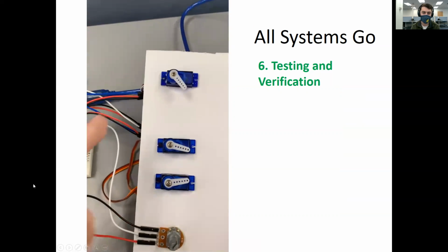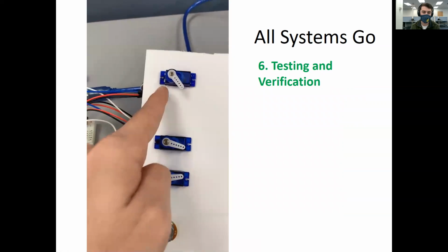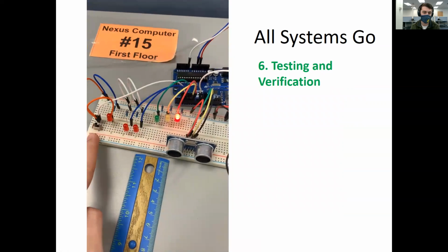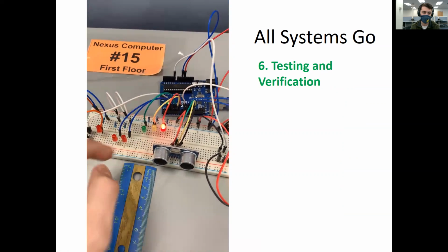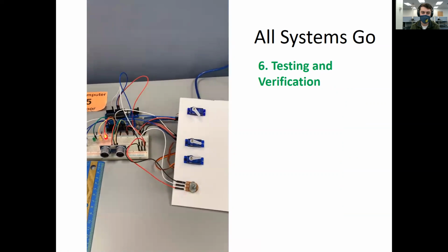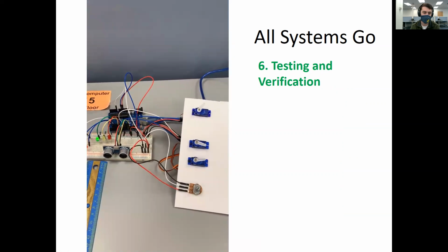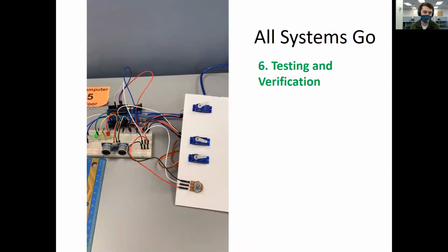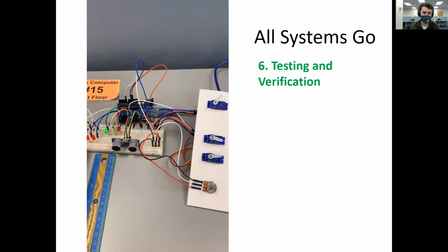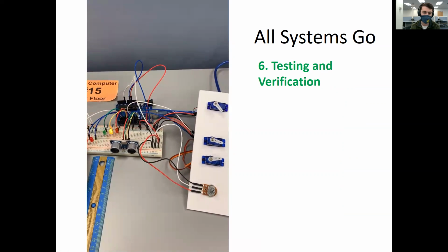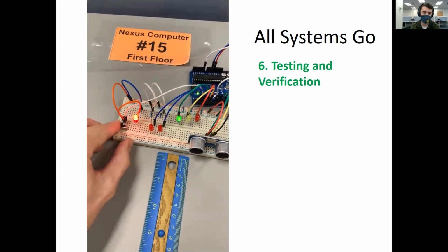So up at the top, we have our landing gear, and that will be controlled by the switch, and it'll have the 3 accompanying LEDs, green, yellow, and red. So when you flip the switch, the motor moves, flip the switch back, and the motor goes back. The LEDs will indicate that position. Green is one position, red is the other, yellow is somewhere in between.